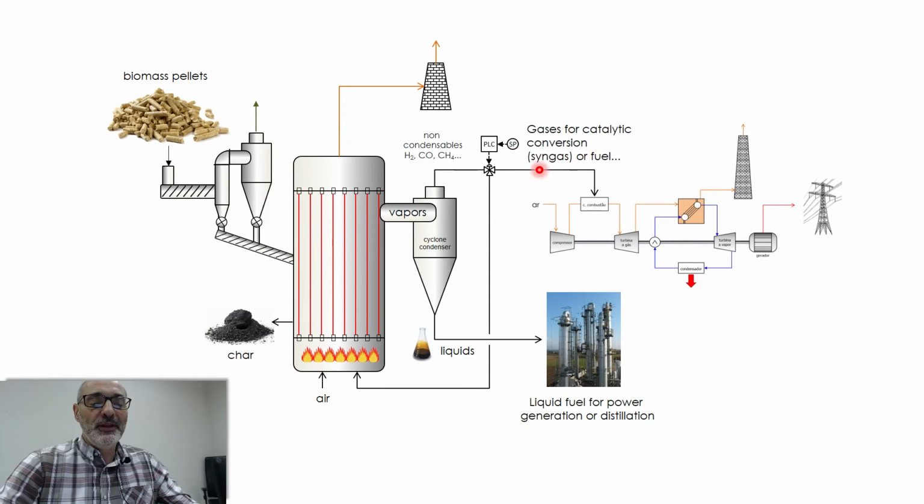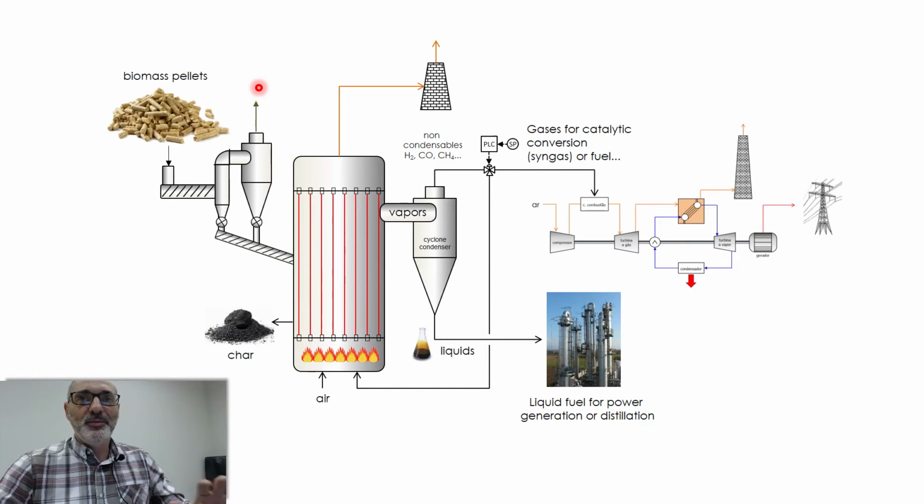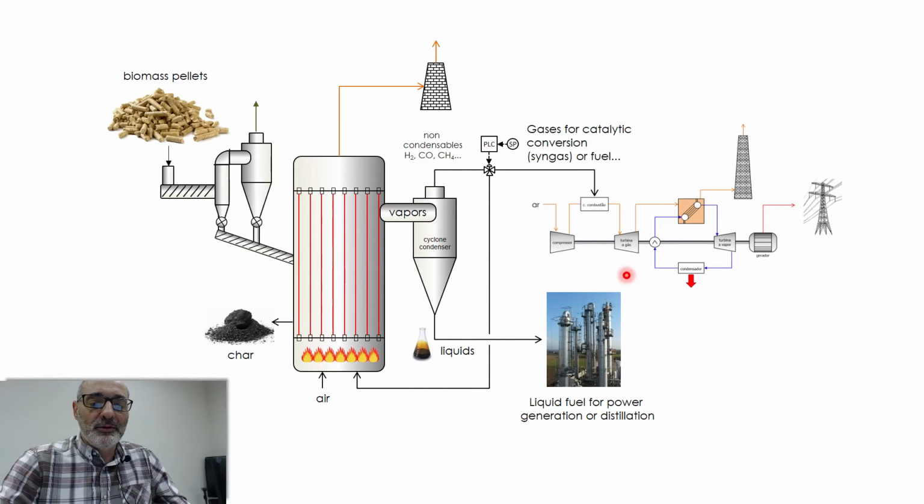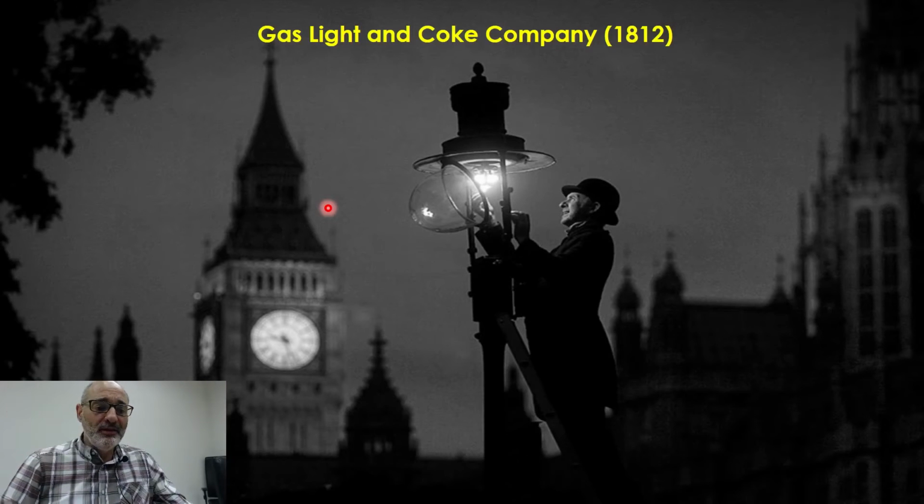power plant. So the feedstock is a gas produced from biomass. So you have a gas cycle from a biomass. The idea here is that I don't want to give you the idea that it's only possible to have a gas power plant with natural gas or biogas. You can drive a gas power plant with biomass, but you have to produce the gaseous fuel from thermochemical decomposition, for instance. This is very old technology.